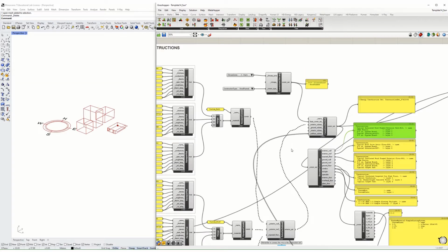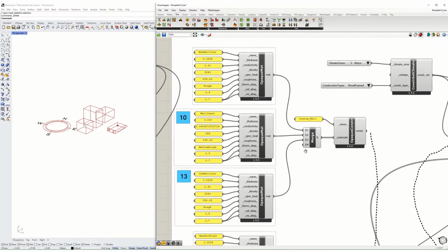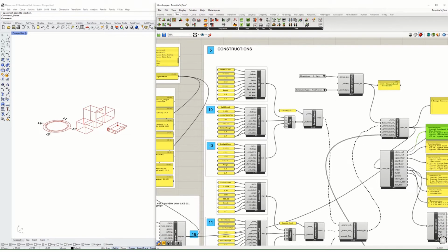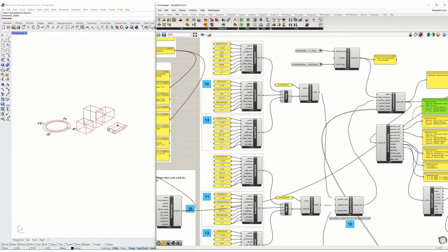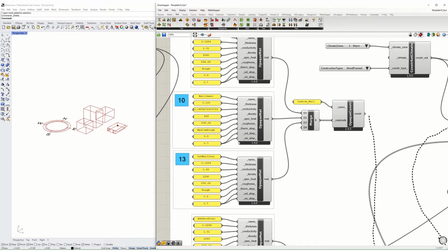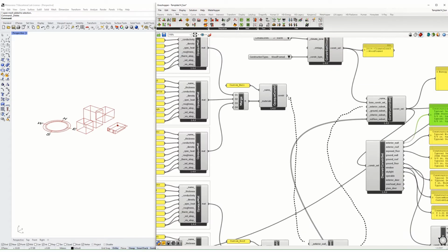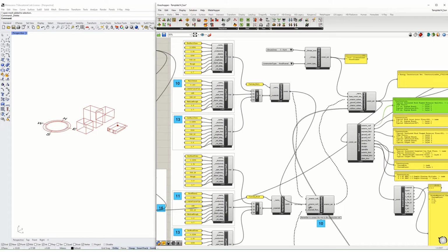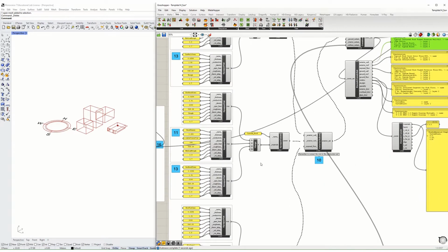If you'd like to use something else, then you can build up these custom walls that I've got for you. Remember the Oreo cookie of thermal mass and insulation and thermal mass. And then, so that's for the walls right there. If you do use that, make sure you connect the construction into this exterior wall and then connect the exterior wall into the exterior subset like that. I'm not going to do that because I'm going to keep the defaults for these sets of runs.